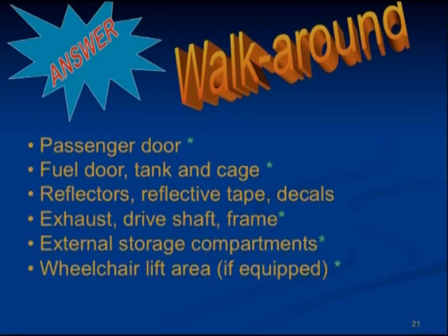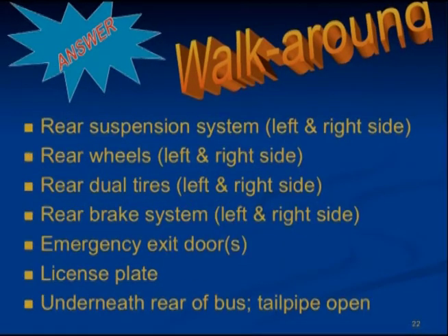For external storage compartments, make sure that they're latched properly. And make sure that the wheelchair lift, if it's equipped, closes and latches properly, and that the lights work and there is nothing unusual. Check the rear suspension, including the frame, spring hangers, leaf springs, that they're not shifted or broken. Check the axles, the shocks, and the mounts for damage or leaks.